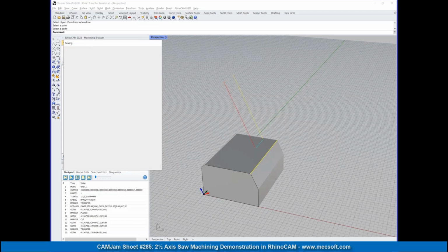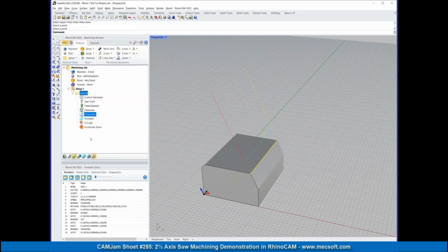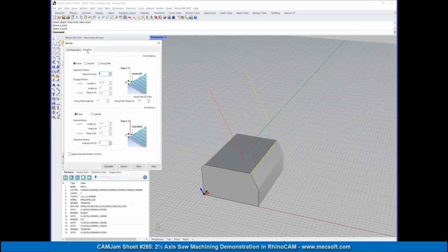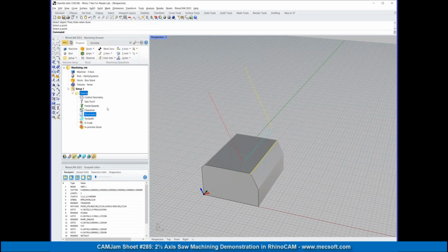So now, is there a way? I guess if for some reason I wanted to extend past, I would just make a curve that was the length I wanted. No, you don't need to make a curve. I'll show you how to do that. You can go to entry exits. You can add a line and an arc, and then you can put an angle or 0 if you wanted. Let me do this first, and then you'll see it's extending.